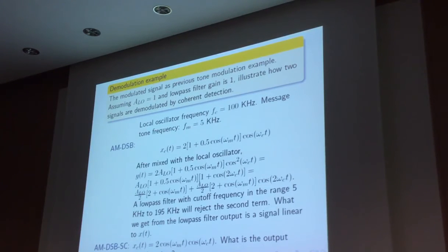Then in the second chapter, we're talking about how to do the modulation. One example is FM modulation, and we need to know why we need to do the modulation. There are two reasons at least. Actually, there are more than two reasons. I just mentioned two reasons in the lecture, all right? One is because of the antenna size. Remember, we have an example, to carry a 75 meters antenna, right? Then another one is to try to avoid spectrum overlap. That's why we need the modulation.